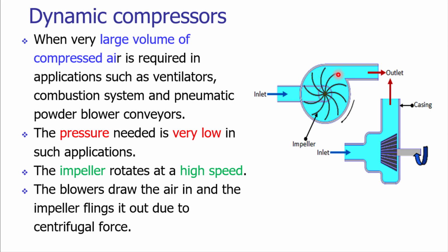As the impeller rotates, and as we are getting the input air at ambient pressure, the impellers push the air, and that pushed air with increased pressure will further lead to the outlet. As the impellers rotate at a high speed, the fluid which has come in is pushed in a radial outward direction due to the centrifugal force. Air will try to move in a radial direction, but there is a casing, and that casing will restrict its movement in a radial outward direction.